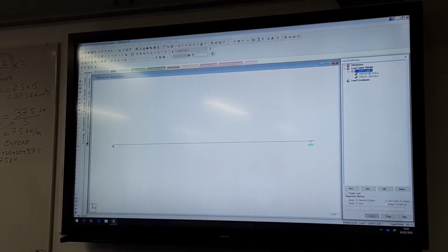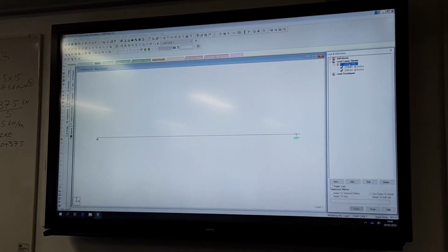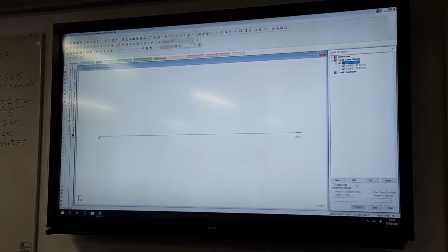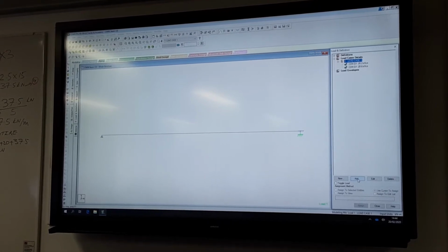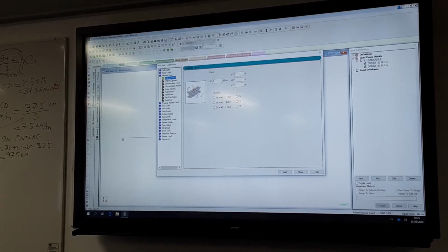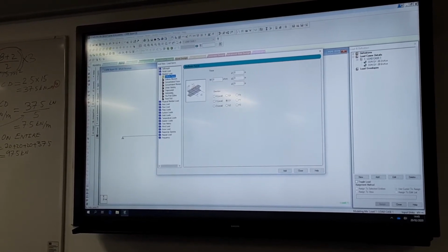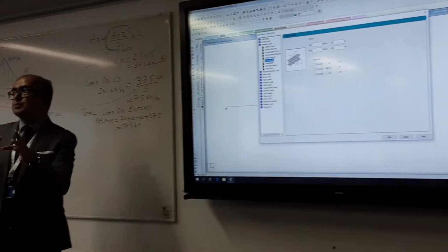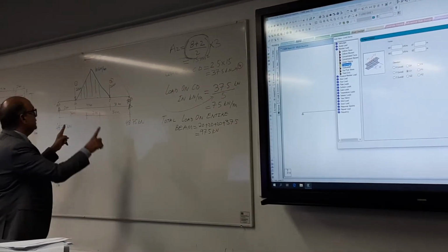Okay. Let's now the other challenge is obviously how do we multiply, how do we add this trapezoidal and triangular loading. So click on add, alright, and click on member loads, and first I would like to go to trapezoidal load. So in this I will simply use concentrated loads and trapezoidal loads. Now first I want to define this triangular load.